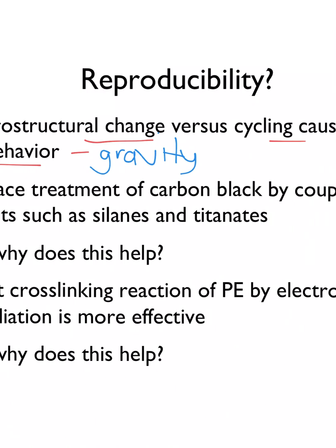Yeah? Polymers are amorphous. Huh? The polymers are amorphous and the carbon is a different density than the HDPE around it, and they could try to settle out a little bit. The carbon could try to separate out of HDPE. So the issue is that carbon is a little more dense than polyethylene.